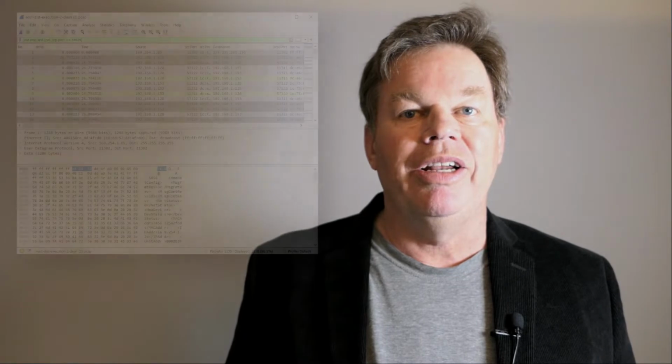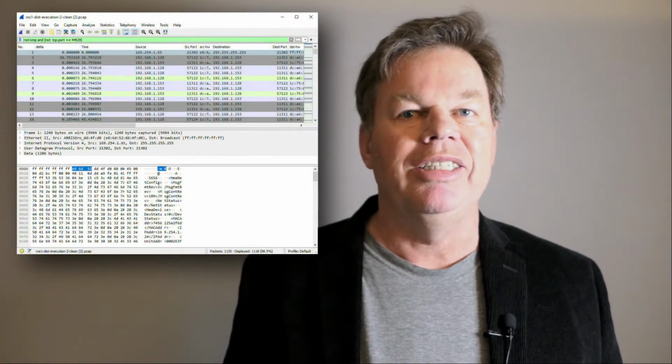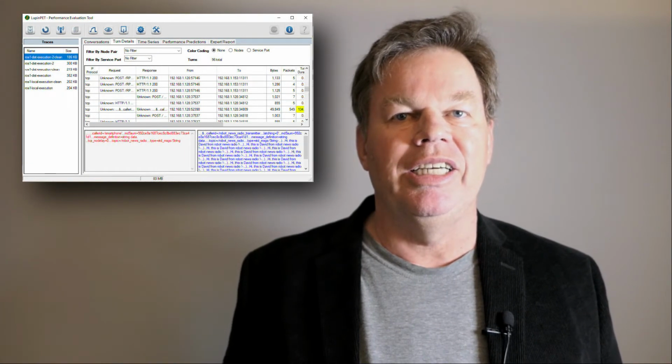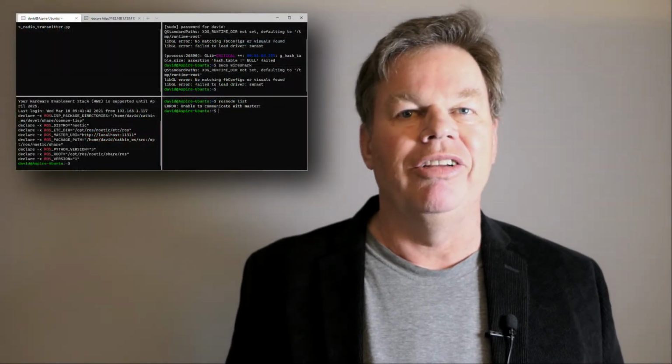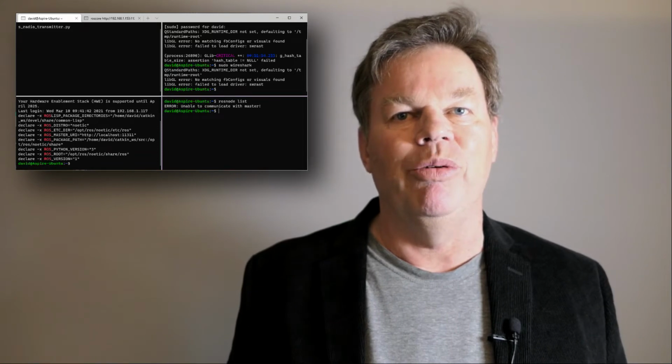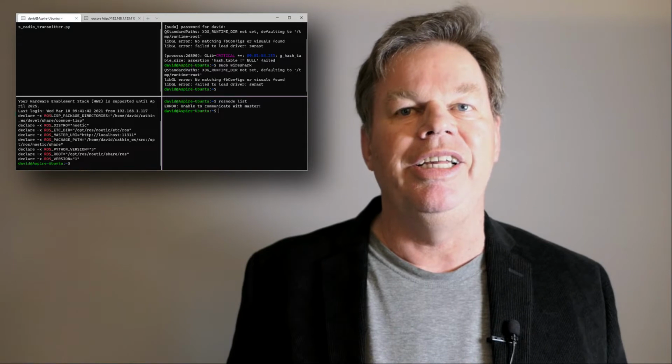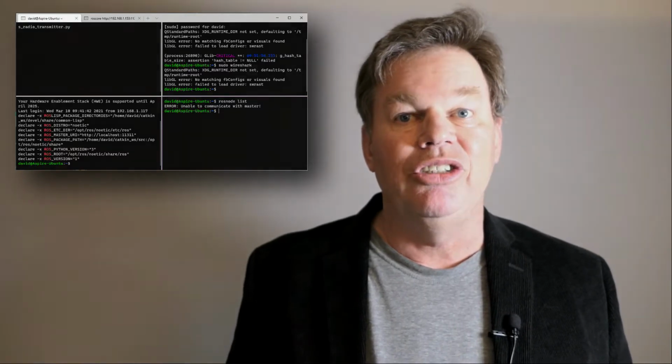So I'm going to pull out Wireshark and some of my network analysis tools, and then run some tests with ROS1, both locally and distributed, to see what it looks like on the network. And then also with ROS2, to see what it looks like when it uses the DDS bus to communicate. So it should be interesting. This is a little sidetrack from most of our bot manager work, but I think it'll set me up to have a better feeling for how to set up nodes and things as I actually construct my robot.